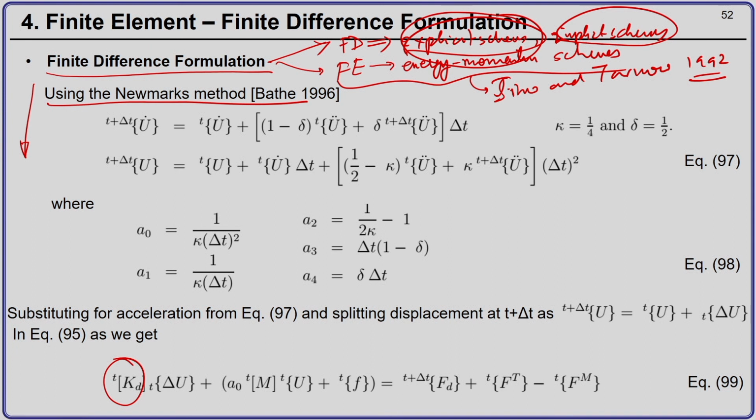So, we do not want to do that, but for certain problems where we do not have strain rate at that level, we can use what is called the implicit scheme. But implicit schemes can be used even for impact kind of problem. It would be accurate, because you will be using Newton-Raphson anyway.